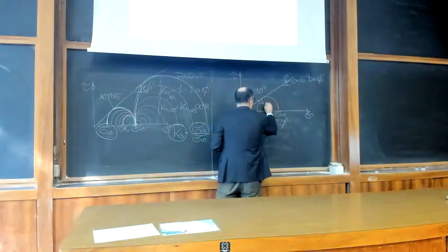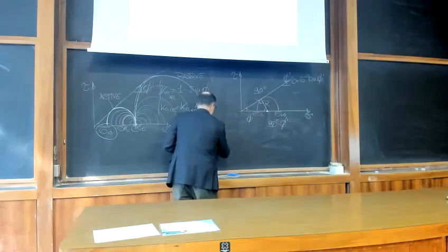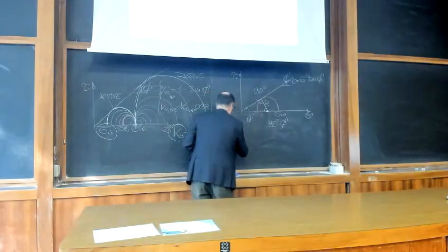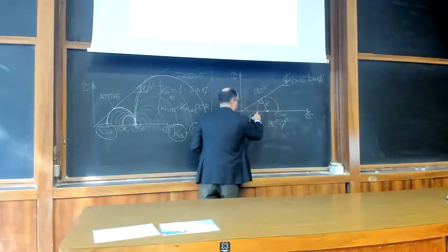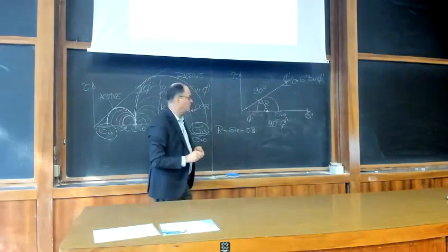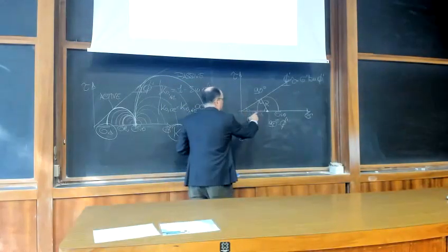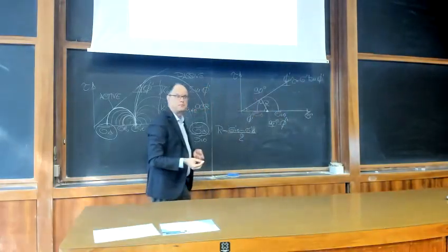You can write, let's say this is the radius of the circle, sigma v naught minus sigma a, which is our horizontal stress, divided by 2. The radius of the circle is the diameter, the distance between this and this, divided by 2.